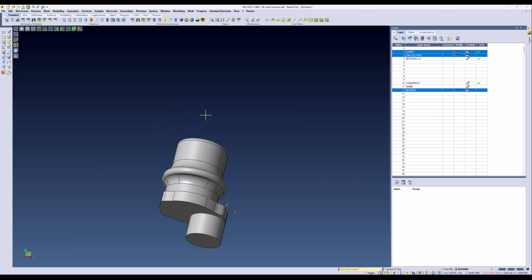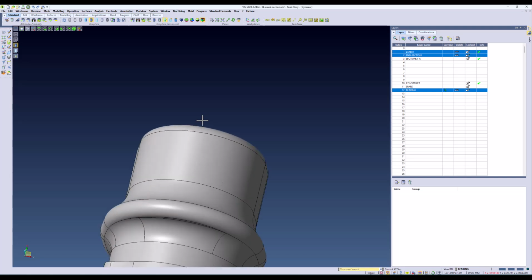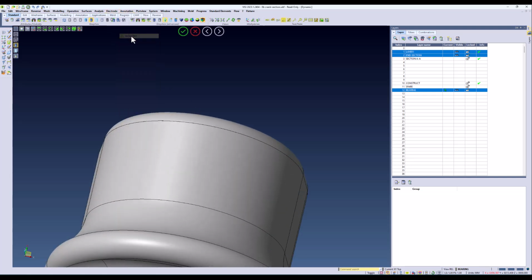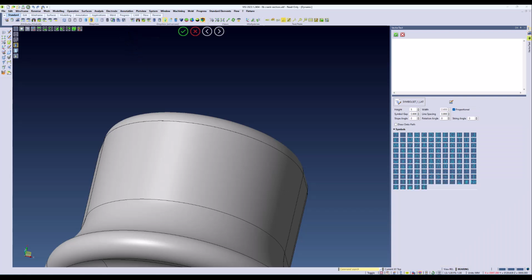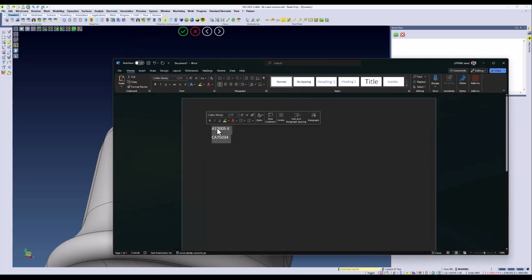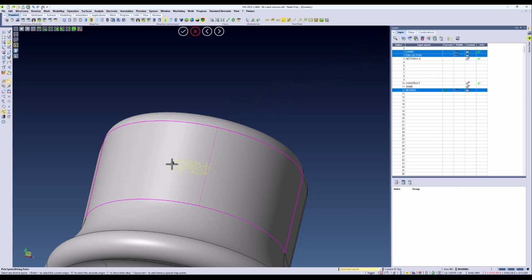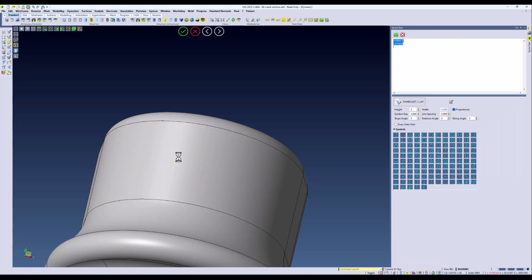It's never been easier to create engraving and model text into a design. So in this example, we're going to use the vector text command. Within vector text, we can copy a part number right onto the model and paste it into vector text. What this command will do is automatically create the text as profiles and curves, and it also creates this text as single line, making it easier for you to be able to do some design work.